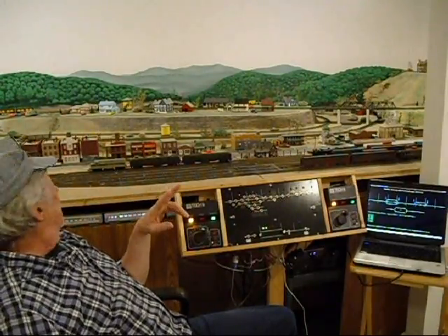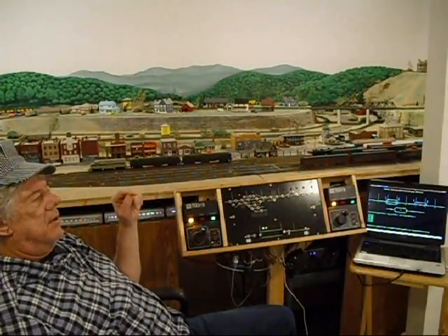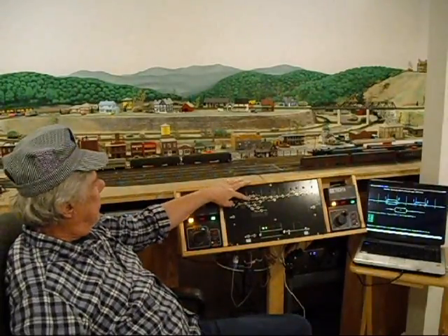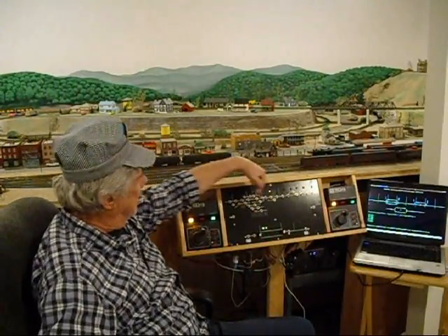It's a little bit complicated, but the way it works is the switch itself, the turnout, actually controls the gap, so that if the switch is set in the wrong position and a train is coming into it, it will stop. In other words, it won't go ahead and derail and ruin the whole thing.